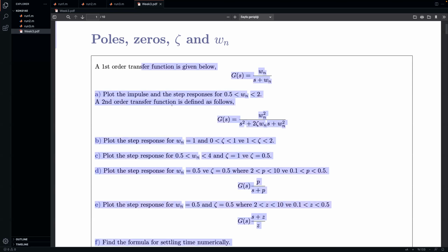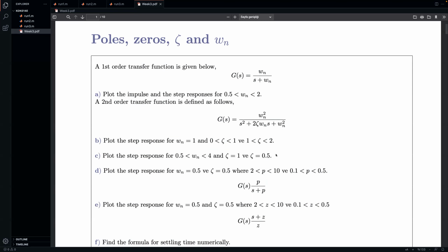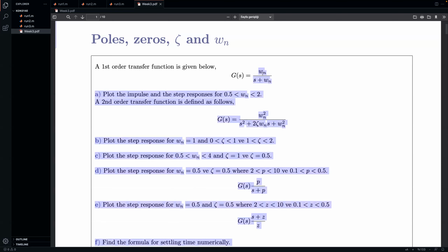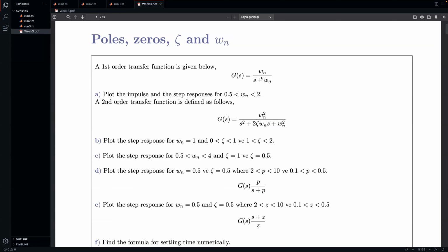Now, up to this point, we've talked about the first order system, the second order system. We did tweak some values and see what is going to be the result looking like. Now, at this point, it is even more important than the previous part, because here we're adding a third pole. And if I'm not wrong, last week we designed a p-type controller using the algebraic method. I've introduced you to the algebraic method and the p-type controller design, and we had a third order system. Now, up to this point, zeta and omega n is just defined for the second order system, and omega n could be basically also used for a first order system.